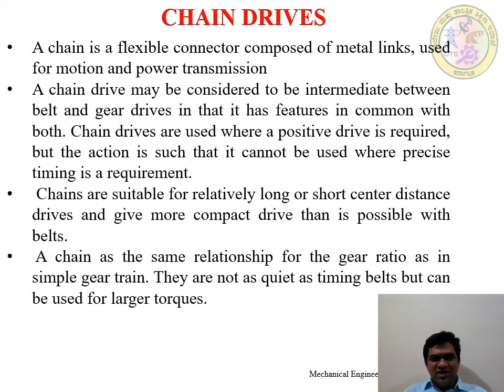So these chain drives are suitable for long or shorter distance drive, and give more compact drive than is possible with the belts. And the gear ratio is similar to that of a simple gear train. So the chain has the same relationship for the gear ratio as in the case of simple gear trains.